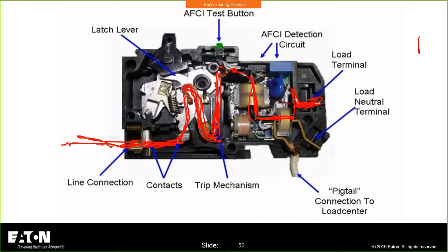And when it bends, to a certain point, it will drop a lever and trip the breaker. And that's your thermal capability. The magnetic capability is when you put a very high fault current through here, you'll pull this, I call it the clapper. If my engineering team was on here, they would just put their head down and go, what did we do? But I call it the clapper, the magnetic forces basically suck this little plate in and it trips instantaneously.